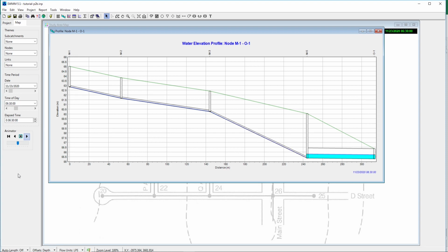day. And as we can see in all the pipes except the larger one, the values of the flow is very small. Of course we cannot use a pipe diameter smaller than 150 millimeters because of the specifications given in the question. So we have to use the minimum pipe diameter which we have chosen, and based on that we can see that in the cross section we don't see much changes there. So let's look at the other results now.